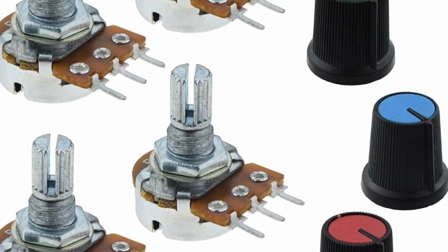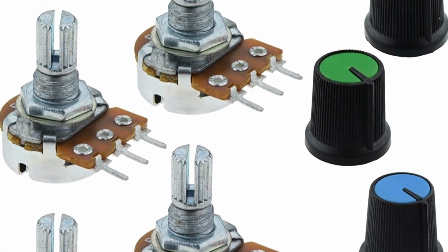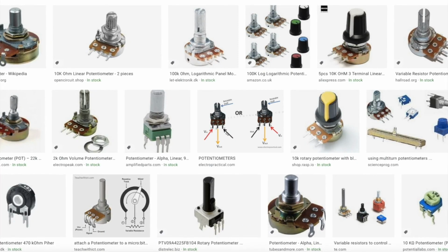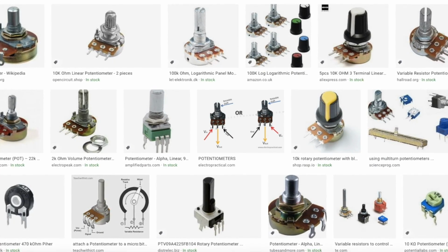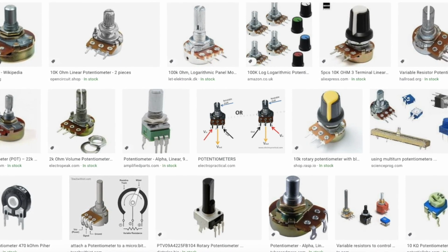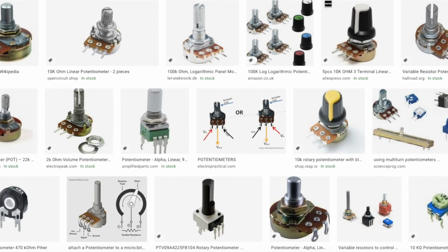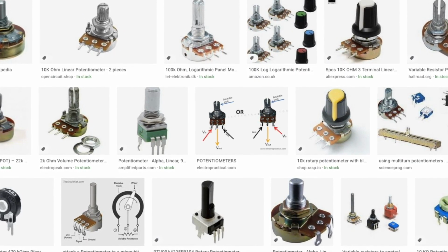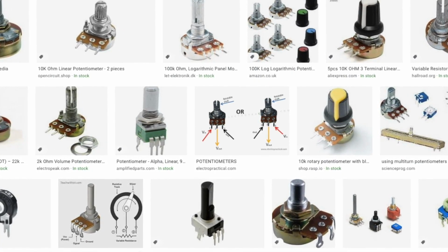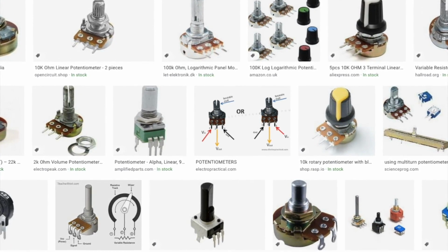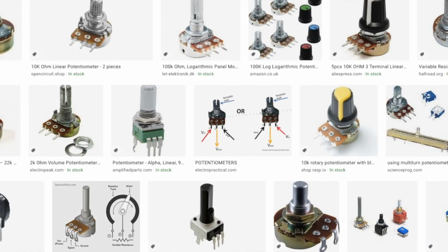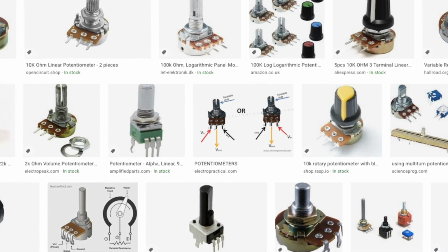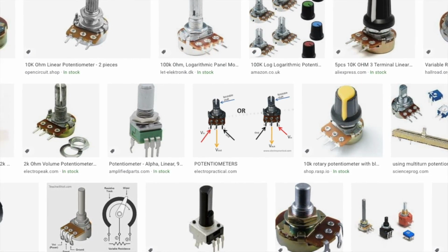The ones that you buy for use as sensors typically let you add your own knob cap to them. There are hundreds and hundreds of different kinds, but each lets you measure voltage across an analog pin, which then changes as you turn the knob. This can be great for controlling things like volume or the intensity of your algorithm's parameters. If you get a contactless potentiometer, you'll spend way more money, but people who use it will be unable to turn it too far and rip the wires out. This can be great for permanent installations.